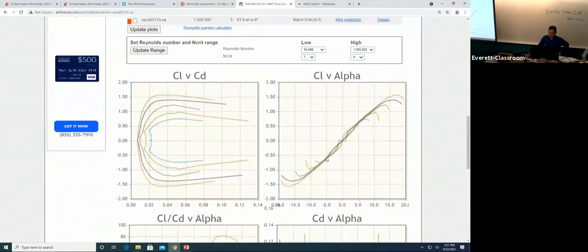What you can see is that for a small angle of attack, say an angle of attack of 0, which means my airfoil is just like that, then this is a symmetric airfoil. So you can imagine for a symmetric airfoil, flat, no lift. And you can see that in fact the lift coefficient is 0. Then the lift coefficient increases almost linearly as angle of attack increases.